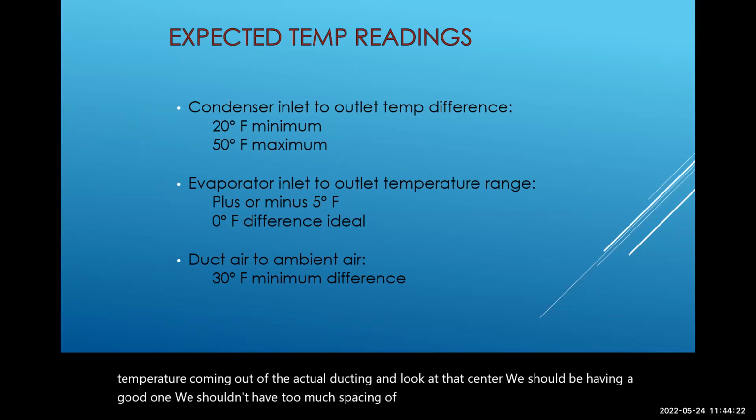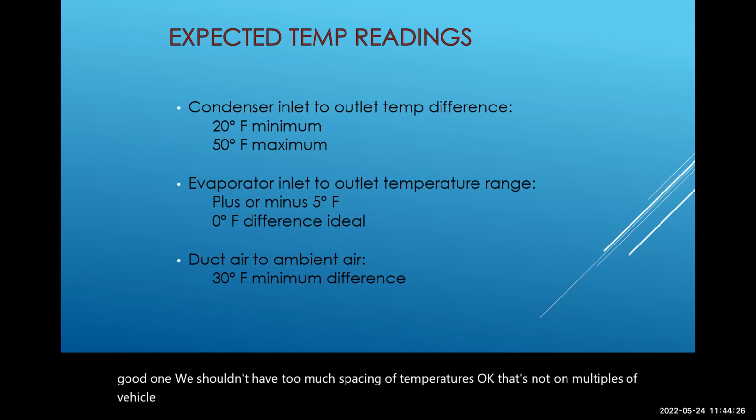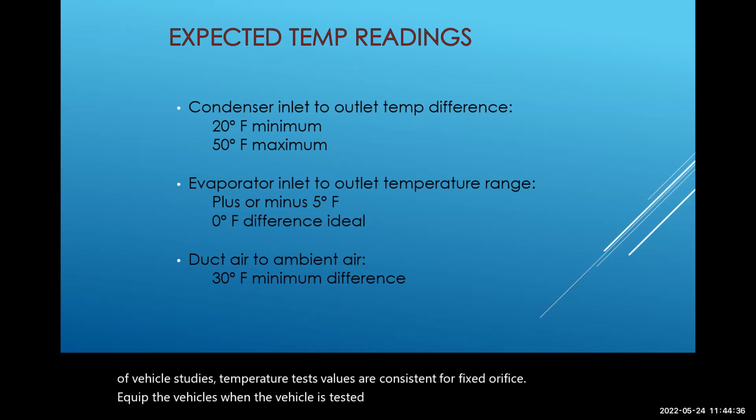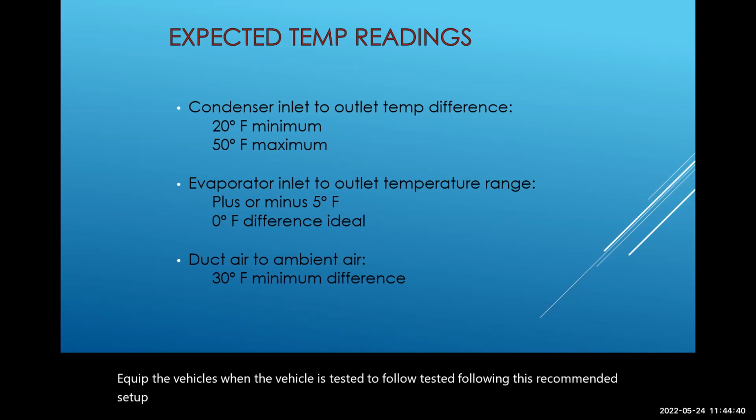Okay. So based on multiple vehicle studies, temperature test values are consistent for fixed orifice equipped vehicles when the vehicle is tested following this recommended setup. When performing temperature testing on expansion valve equipped vehicles, evaporator inlet and outlet tests are not performed.